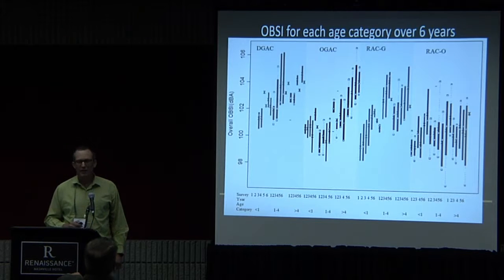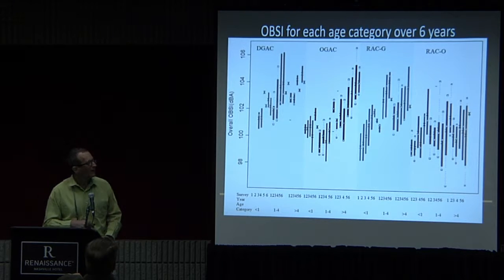Because we didn't have a density-based compaction spec. We had a method spec, and what we found out is our gap-graded rubber was basically open-graded until traffic turned it back into a gap graded and drove the air voids down from 12% to 7% in the first 2 years of traffic. We now have a density spec on this, which we think will make that gap graded, a great performer for reflective cracking, even better.